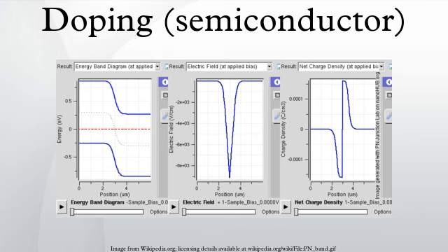Techniques of doping and synthesis: the synthesis of N-type semiconductors may involve the use of vapor phase epitaxy. In vapor phase epitaxy, a gas containing the negative dopant is passed over the substrate wafer. In the case of N-type GaAs doping, hydrogen sulfide is passed over the gallium arsenide, and sulfur is incorporated into the structure. This process is characterized by a constant concentration of sulfur on the surface. In the case of semiconductors in general, only a very thin layer of the wafer needs to be doped in order to obtain the desired electronic properties.